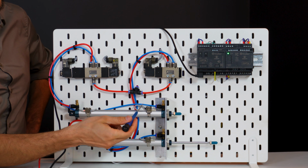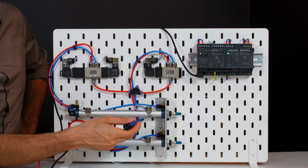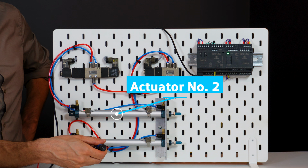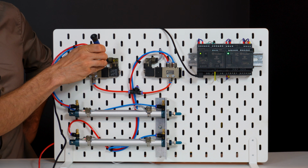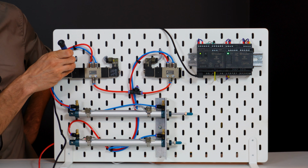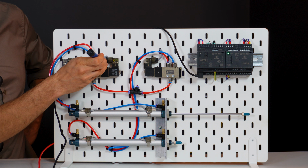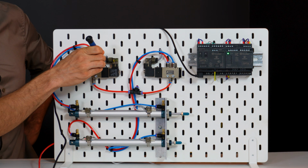This actuator is equipped with 2 limit sensors, the home position and the extended position. Similarly, we will control actuator number 2 using this 3-position distributor. Activating the coil on the left side causes extension, while the return is triggered by the second coil.